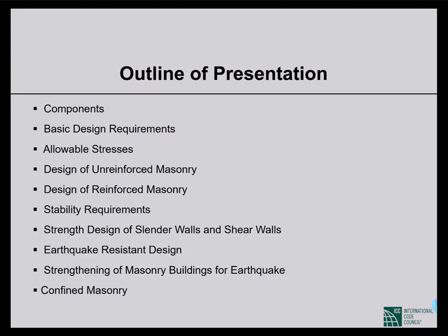Remember, the basic design philosophy for masonry structures is based on the working stress design method, but for slender walls and shear walls, a designer can adopt the strength design method too. Then we'll discuss some important issues of earthquake resistant design of this type of structure. Then a very brief mention of strengthening of masonry buildings for earthquake.